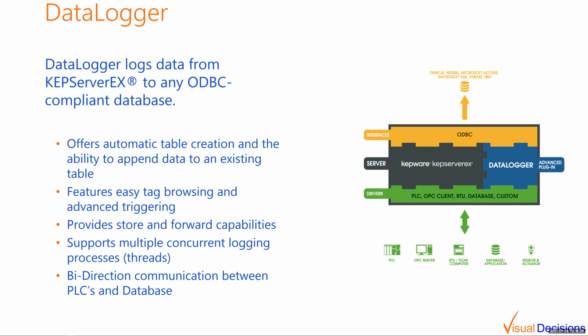The data logger does pretty much exactly what it sounds like. It logs data from the Kep server to any ODBC compliant database, such as SQL Server, Oracle, MySQL, Postgres, or pretty much any ODBC compliant database that's out there. It provides substantial benefits such as simple installation, high efficiency performance, easy tag browsing, advanced triggering, and store and forward capabilities.